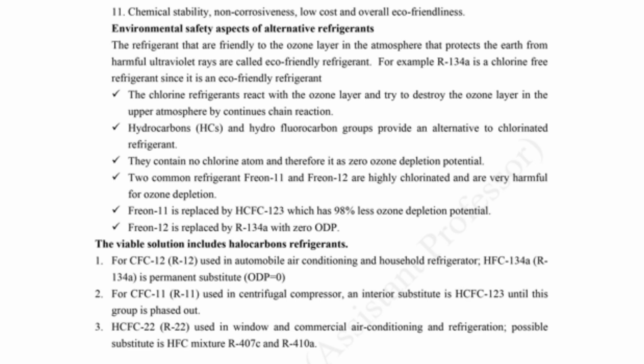The viable solutions include halocarbon refrigerants. For CFC 12 (R12), used in automobile air conditioning and household refrigerators, HFC 134a is the permanent substitute with ODP equal to 0.